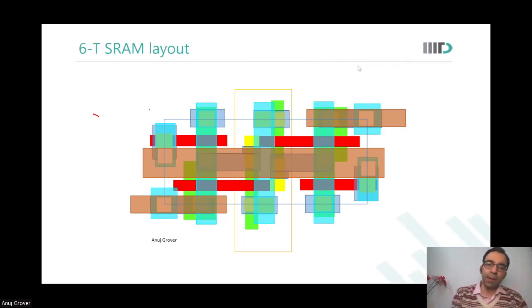And the ground stubs you will notice are also just stubs. In metal 2 they are simply stubs. Even in metal 3 they are simply stubs. So we need to provide power. For that I had probably shown the metal 4 vertical line there, and the connection for ground was provided there, but we did not show anything for VDD.